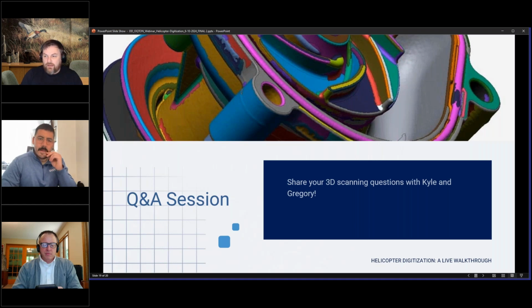Absolutely. There is a piece of functionality within Design X, once you create these components, where you can live transfer it over into CAD. What it'll do is build the history tree over there, line by line, the sketch and the feature, inside of CAD. So that's how you get that over there, by live transferring it. And it supports SolidWorks, NX, Pro E, Inventor as well.